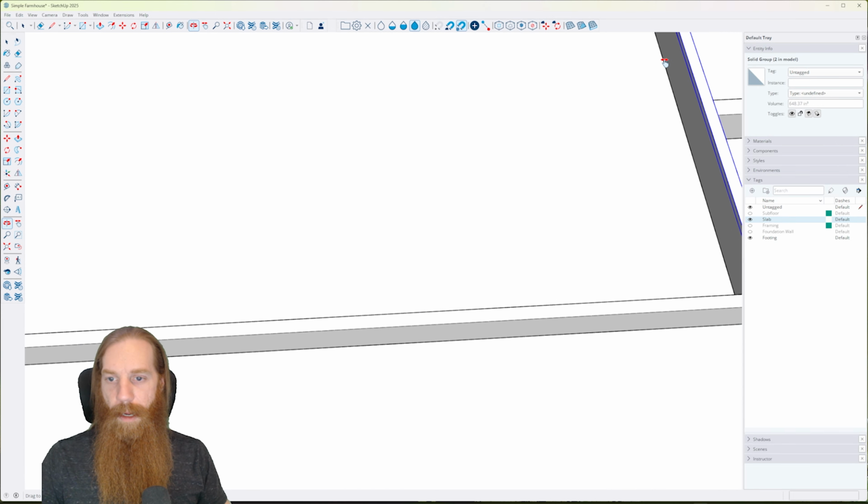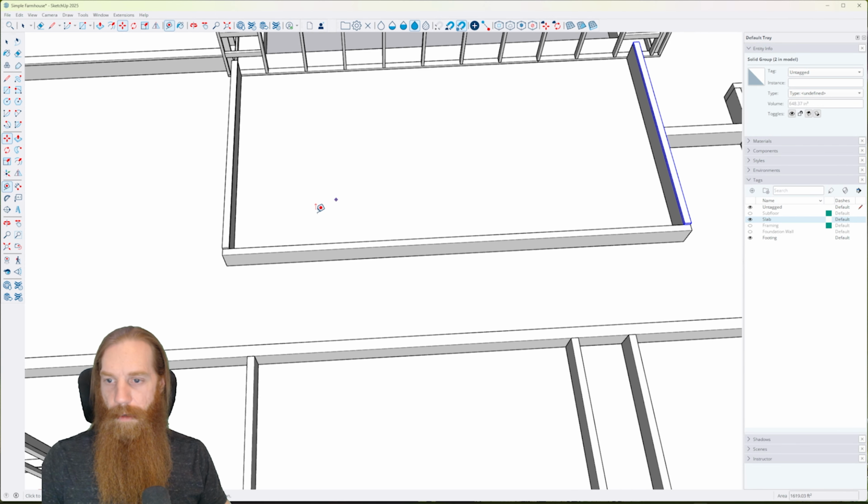Now this wall here, let me see, how long is this wall? Do we need to do 2 separate pieces? Yeah, it's 20 foot. So let's go ahead, and it's almost worth it to actually split this wall into 2 12-foot pieces. I mean, not exactly 12 foot, but using 12-foot boards for this instead of a 16 foot and then a small little 4-footer. We'll just go with the 4-foot. I think that's fine though. So we'll do a 16 foot.